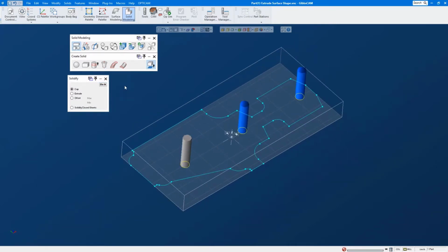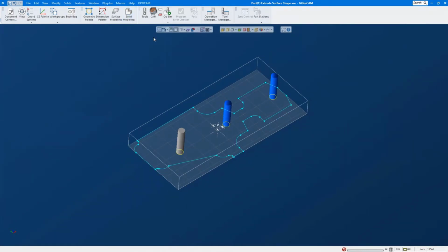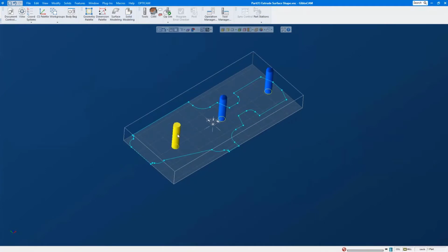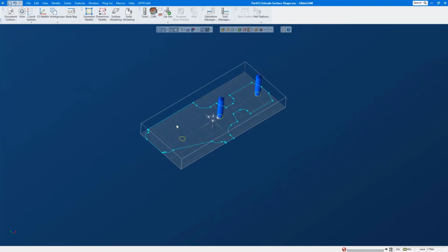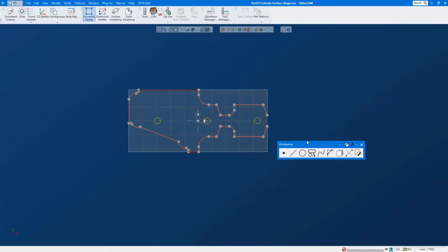Okay. Steve, can you do this also with multiple geometries, not cylindrical geometries? Yes. I have tried this, no success. If you make the same geometry in blue with the offset, make an offset and try to select both geometries and try to extrude this.